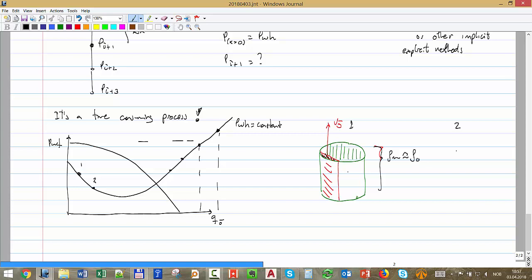Now in point 2, the velocity starts to increase, overall, the velocities of both the gas and the oil. If we take just the oil part, what is really helping the oil to flow is the shear that the gas makes on that face. You have here some force, let's call it shear force, tau, that is dragging the liquid up.